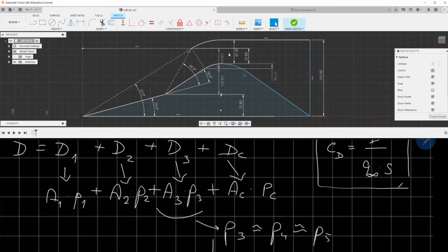I see. I was having some trouble with that because I was kind of confused about the definition for compressible flow and the changes in pressure, since I found the Mach number bigger than 0.3, so the flow there would be compressible. But since the Mach number doesn't change along this section, there wouldn't really be much change in pressure.